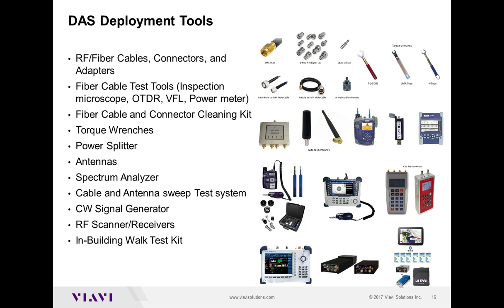I mean, because it significantly reduces your load when you are carrying out to the field, right? Although it is double the cost most of the time. Then you have RF scanners and receivers. We talked about it. You have to capture the signal, and of course then a good lightweight in-building walk test kit for the last phase, when you are trying to basically validate the performance of the DAS network.